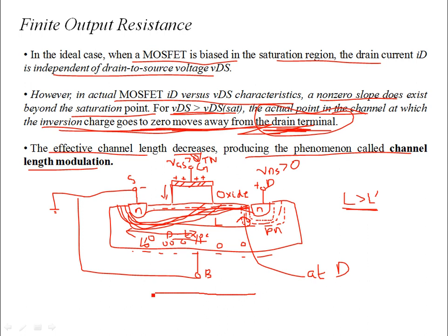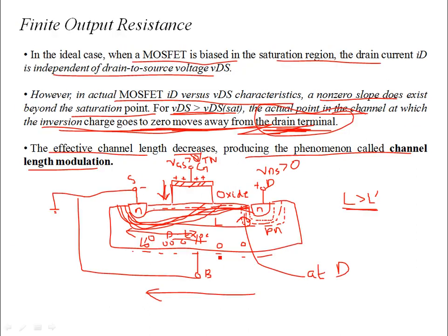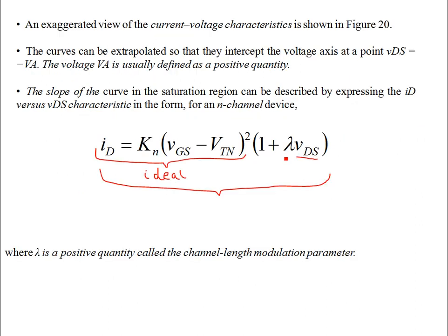So the horizontal electric field is like this, which is going to be there in the channel, and it's responsible for the mobility of negative charge particles, and that's the perpendicular electric field due to the gate. So this horizontal electric field is responsible for moving the charges along the channel. This is due to VDS, and we are now considering the effect of VDS on the channel length modulation.